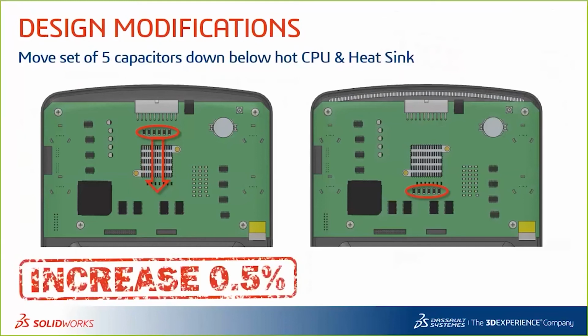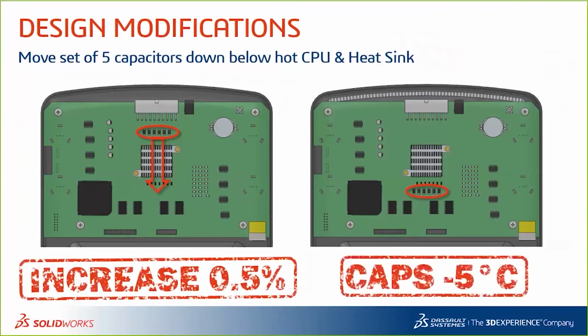Moving the capacitors below the heatsink did increase the heatsink temperature by 0.5%, but that's okay. That's the whole purpose of a heatsink. But we were able to reduce the capacitor temperature by 5 Celsius, which is a significant savings in that temperature plot.